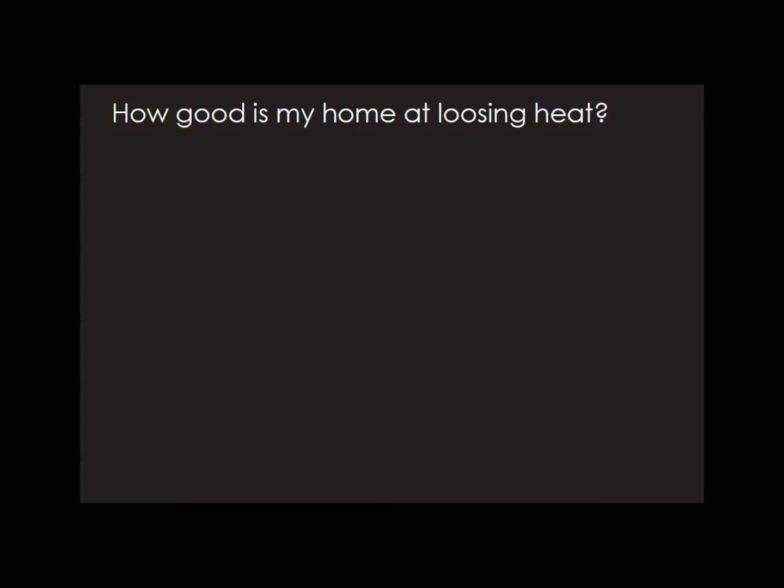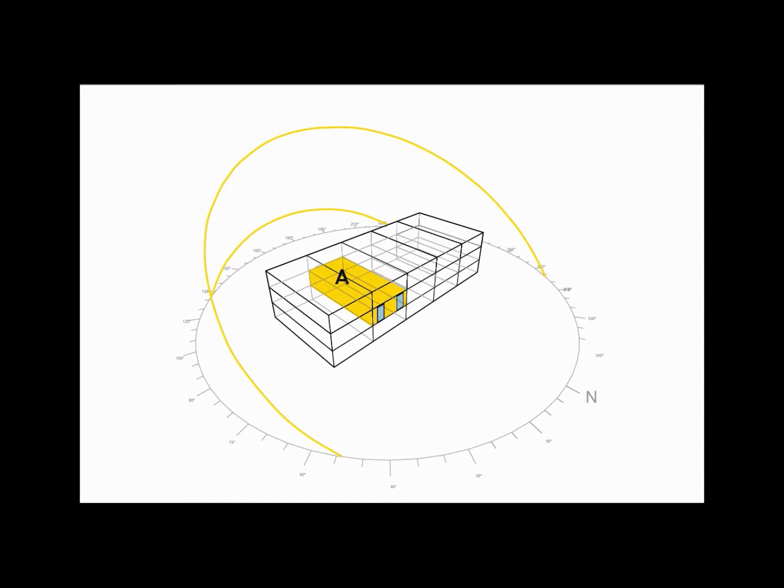Okay, in the lecture we looked at one quality of passive design, particularly with respect to London. That was the quality of heat loss, and how we can address that through some very simple strategies. So we looked very quickly at three different apartments, and we made the point, which I think everybody got, that between these three apartments, A, B, and C, the fundamental difference was, although they're the same size and same shape and same windows, how much of those apartments relates to outside, so what we'd say the external facing part of the envelope.